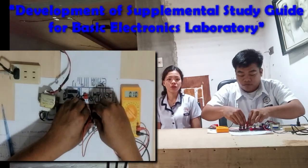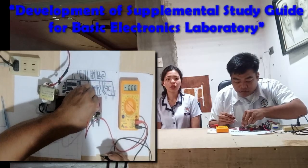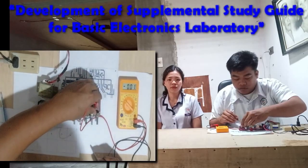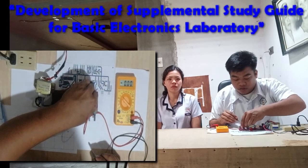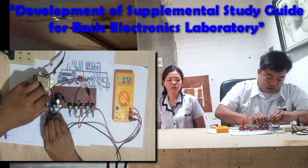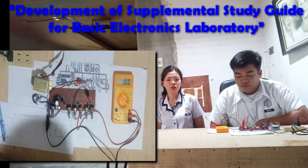Fifth, without disturbing the setting of R1, adjust potentiometer R4 until the transistor emitter to collector voltage is equal to 1 volt. Now measure the voltage across R3.